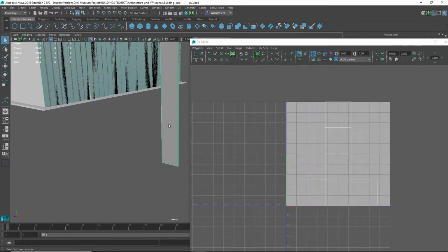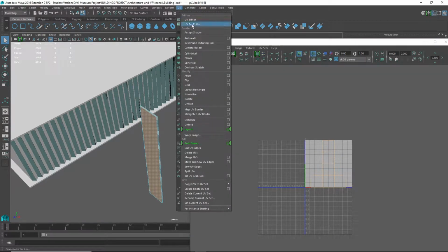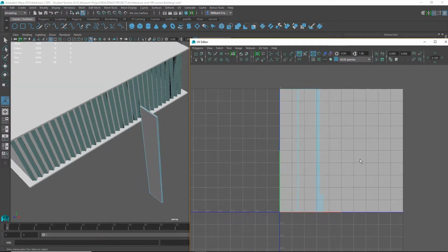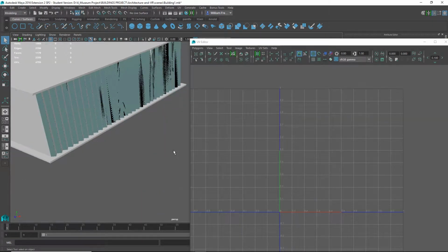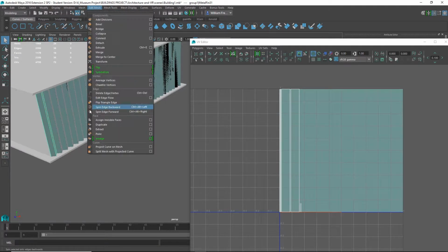So if I want to do that to this box that I just made, just to illustrate what it would look like now that I've stretched it out, if I say face, select all the faces, that selects all the faces on the box, and then automatic, you notice that its UVs are now laid out appropriately. The nice thing, and something I didn't know about, but it's sort of nice in Maya, is that if you look at this in the hypergraph,